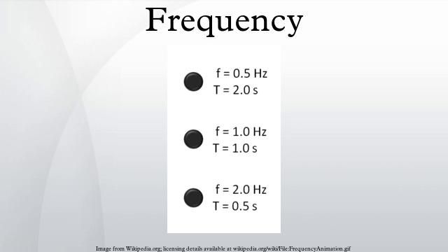It uses digital logic to count the number of cycles during a time interval established by a precision quartz time base. Cyclic processes that are not electrical in nature, such as the rotation rate of a shaft, mechanical vibrations, or sound waves, can be converted to a repetitive electronic signal by transducers and the signal applied to a frequency counter.